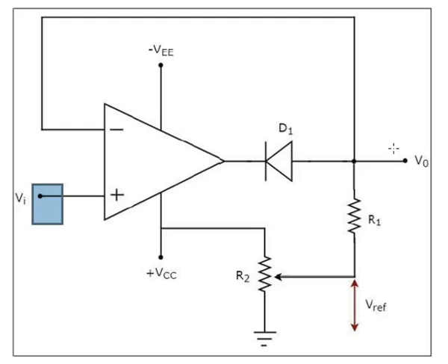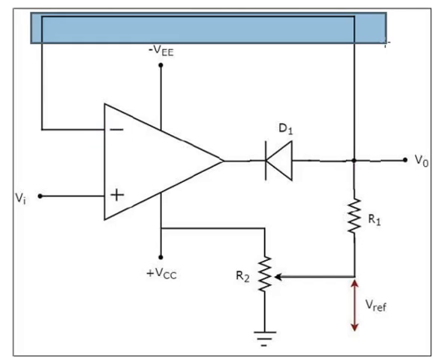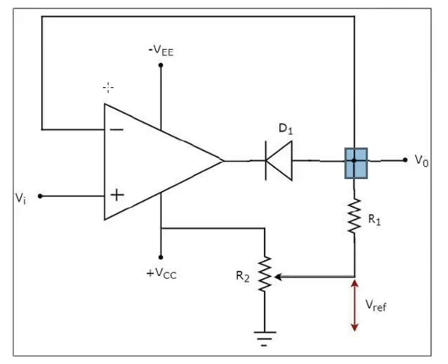Here is the output voltage, followed by a PN junction diode, and shorted with the feedback from the output voltage to the inverting terminal. So we haven't used any kind of resistance. We simply short the output voltage with the inverting terminal.